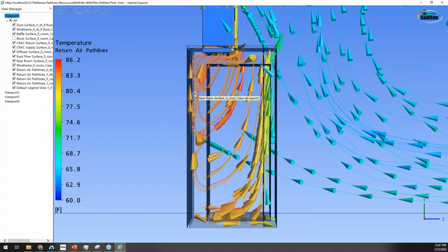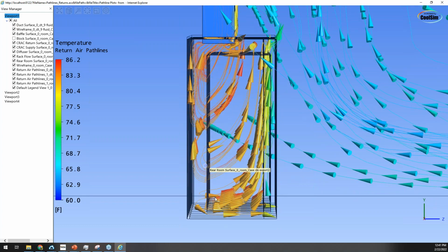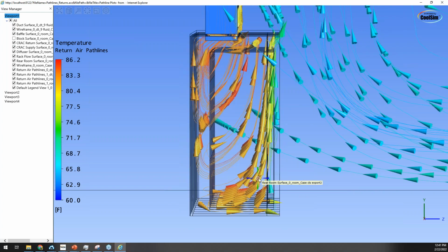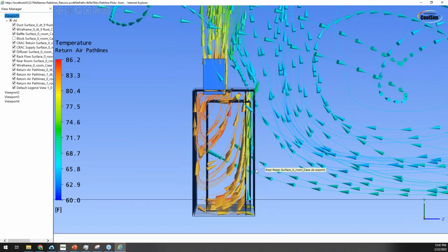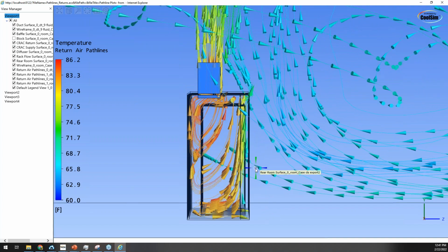It's bouncing off that back wall and it's creating pressure, right? Because we went from high velocity to no velocity. So any dynamic pressure got transferred immediately into static, and it's pushing. And guess where it's pushing? It's pushing on the front of that, pushing out the front. And this is just a normal chimney sitting on top. These are what we call passive chimneys.